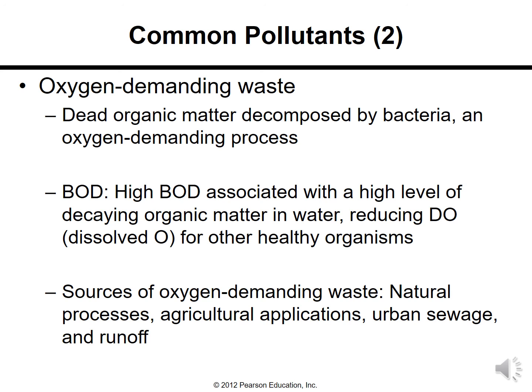And BOD, biological oxygen demand: a high BOD is associated with a high level of decaying organic matter in water, reducing dissolved oxygen for other healthy organisms. Sources of oxygen demanding waste: natural processes, agricultural applications, urban sewage and runoff. So these are the sources of oxygen demanding waste.